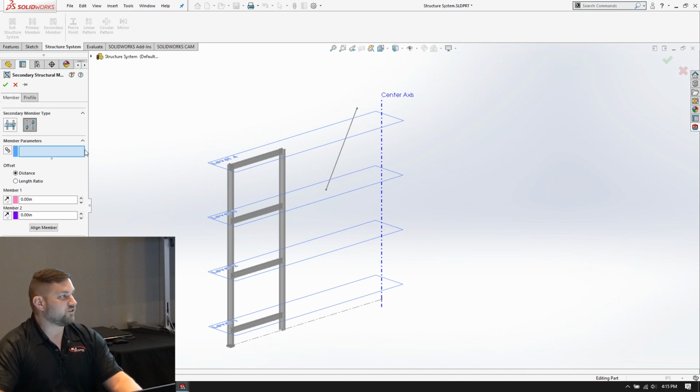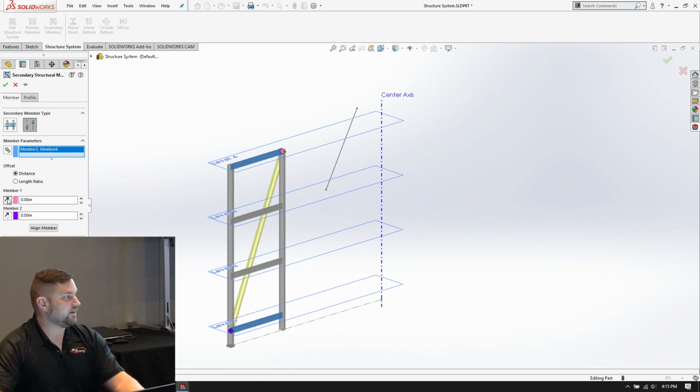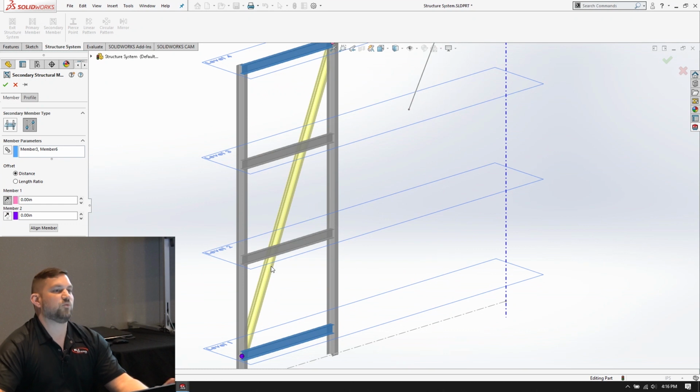Now this time, this is something that's brand new for 2020, is the ability to go between 2 existing members. I can say that I want them to go from the ends of this, but alternating ends. And then if this thing is traversing those 2 middle pieces like what you see here, that can cause a problem whenever you get into trimming. And it's going to be a lot of manual trimming and clicking and rotating of the model. We don't want to be moving our model all around. We want to be efficient. So I'm going to say that I want to break it with those 2 pieces of geometry. So it's going to split the model for us.